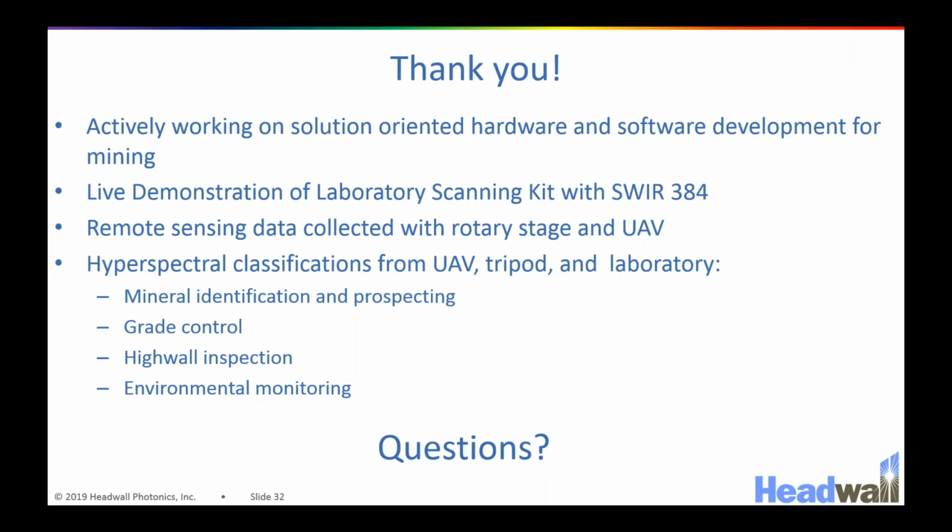Yes, if we sell you a turnkey system, so a system integrated onto our drone, we always fly it before it ships out the door. And so we'll set the orthorectification offsets ourselves. When it ships to you, it will have standard orthorectification offsets already in there that were made at our facility, but you do also have the ability to adjust those offsets from scan to scan to dial in if there are slight differences from one run to the next.